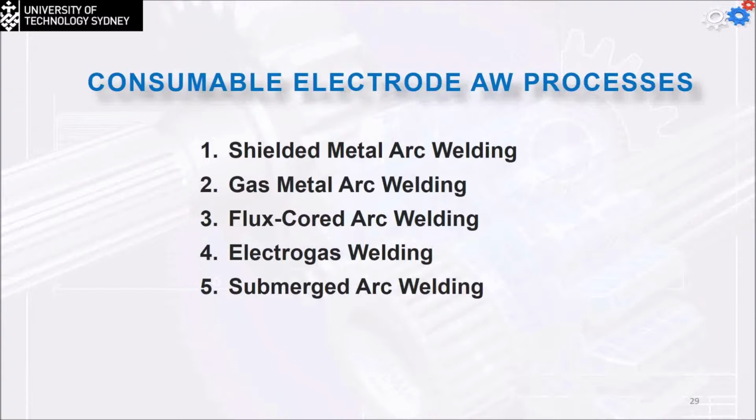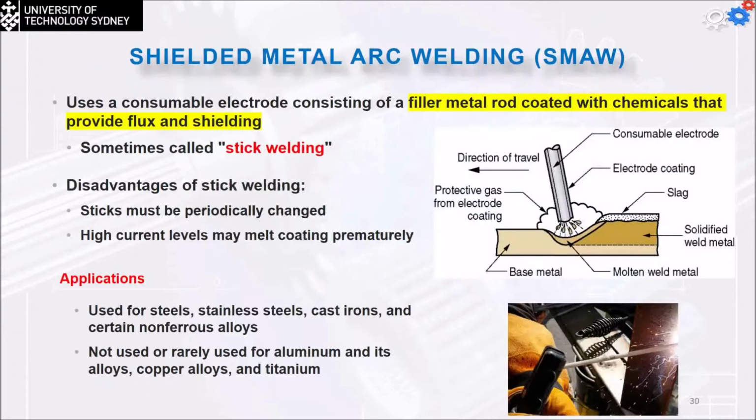The same stick we saw earlier is going to be used. Once again, we're going to run the current. We're going to have a small gap. When you do this process, you have to mind the gap. Usually professional people can handle it very nicely. If they have direct contact, no welding will happen. It will stick on the machine.